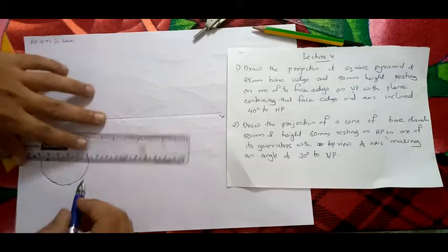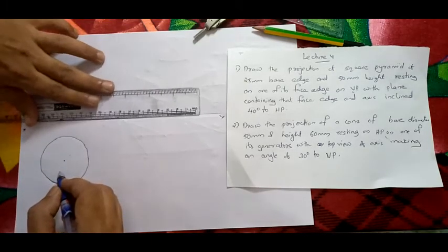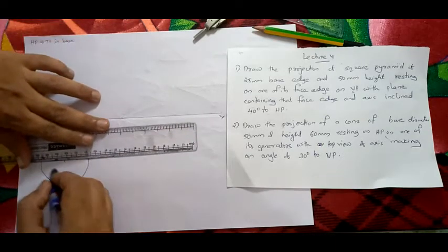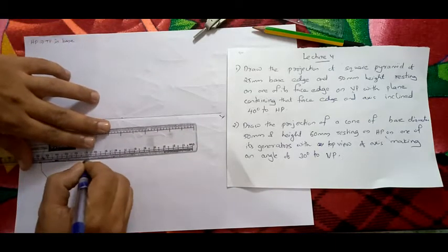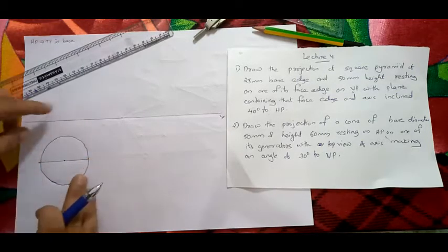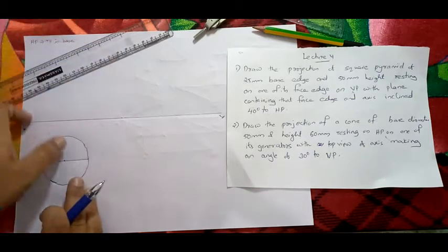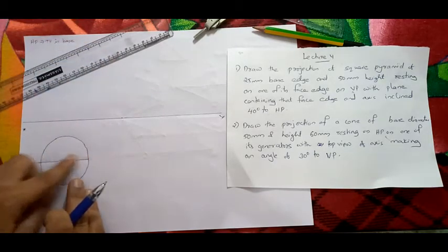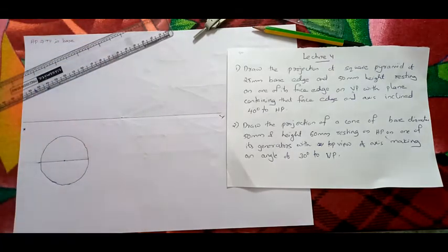So next what you have to do is, see, draw a line parallel to this XY line. Draw a line parallel to this XY line here. This is the leftmost point and rightmost point of the circle. So by using the roller scale, you draw a parallel line passing through the center, that is the diameter you have drawn, to find the leftmost and rightmost points. If you rotate the circle, you will get an ellipse-like structure. An ellipse you cannot draw with two or 4 points, right? You need more points. For that purpose, we will be dividing this into 8 equal parts.